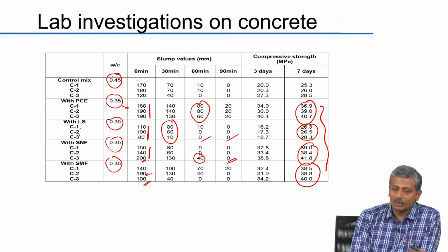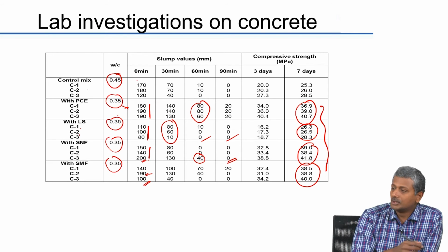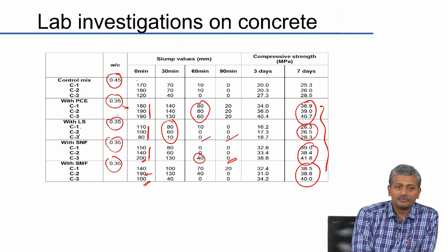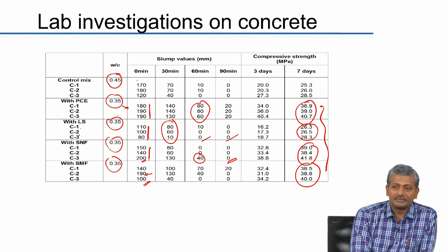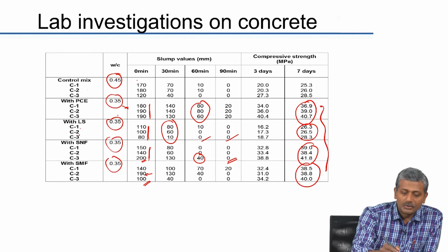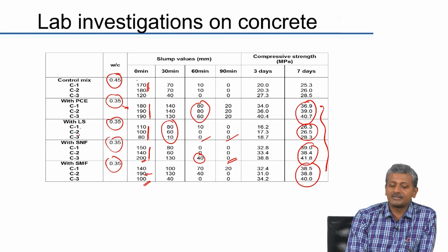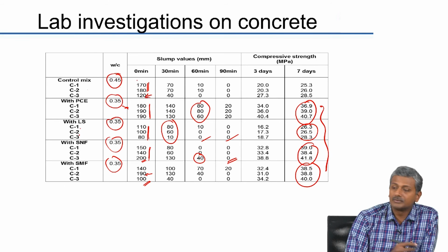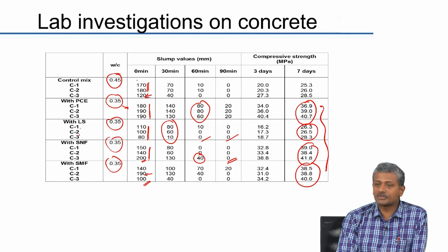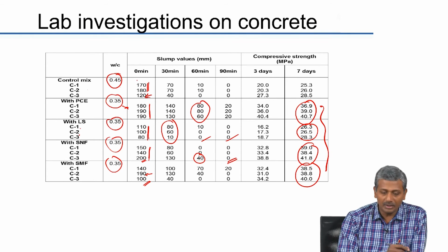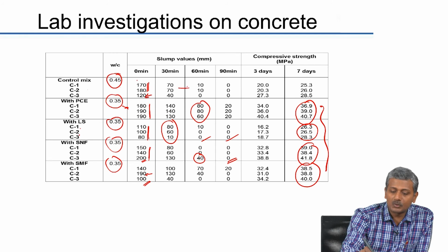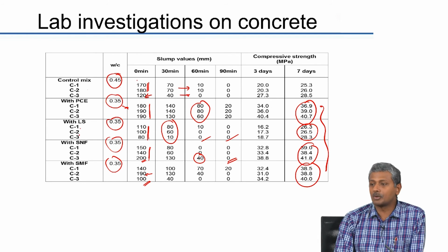Okay. So, essentially we are looking at a water reduction of how much? 0.1 water cement ratio, that corresponds to about 20% water reduction. Okay. So, at 0.45 water cement ratio, my slumps were high with the C1 and C2, but lower with the C3. Why? C3 was finer, okay, finer cement. So, obviously the slump is reduced. Okay. The slump retention again was quite poor, because by 60 minutes your slump is almost down to 0.